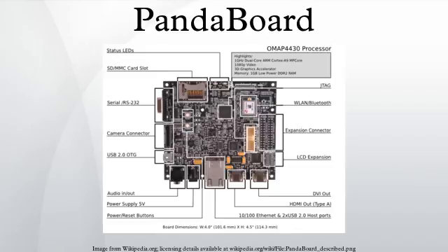Clock: the PandaBoard has a real-time clock, but it does not have a battery to save the time when power is removed. As an alternative, a software clock can set the clock time at boot up based on the time of the last modification to the file system, so that time stored in files will be more reasonable. NTP can set the correct date and time if the PandaBoard has network access to an NTP server.